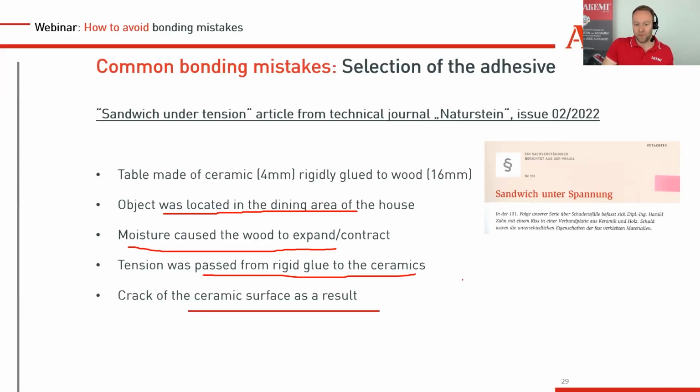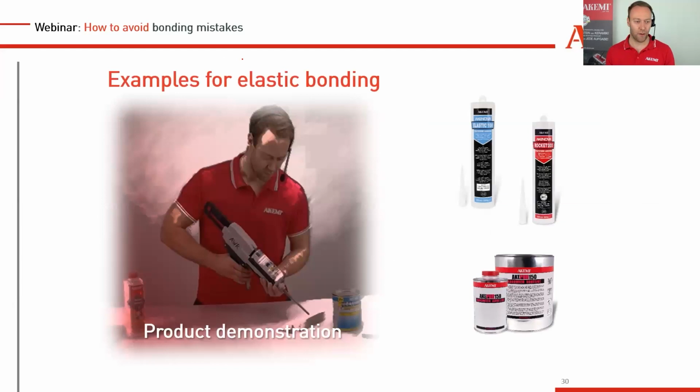So it's not only the heat you have to have in mind, it's also the substrate itself. If they had used aluminum honeycomb for that application, interior-wise, maybe nothing would have happened, because aluminum does not absorb any humidity. But they used wood, which absorbed moisture, started to bend, and then the problem occurred. So just have it in mind: with different substrates bonded together, you have to be aware of humidity and heat expansion. Okay, and I think what could be some solutions for that, we show in our application table.